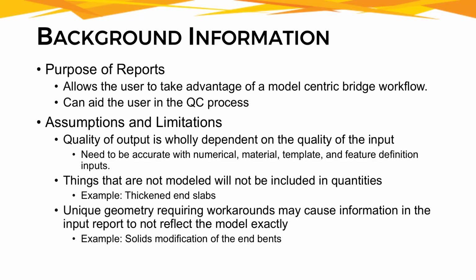So for instance, when we're talking about the quantity reports, the appropriate feature definitions, templates, material types, and numerical inputs all need to be correct when initially creating the model. This will allow you to create a more accurate quantity report. One of the things that the user also needs to be aware of is things that are not modeled are not going to be included in the quantities. One good example of this is the FDOT workflow currently does not model thickened end slabs. So in the deck concrete quantity, those thickened end slabs will not be accounted for.